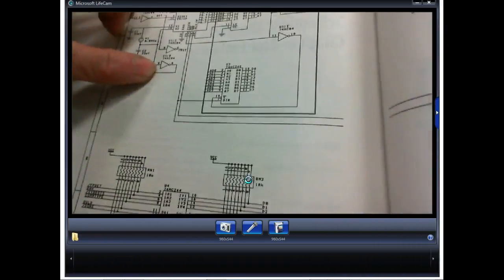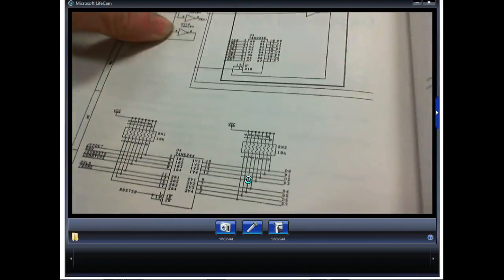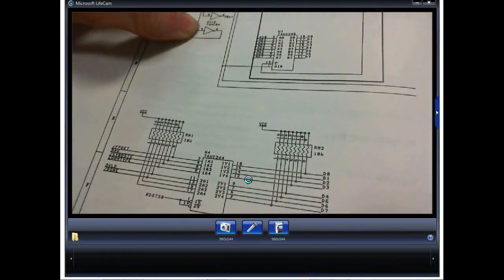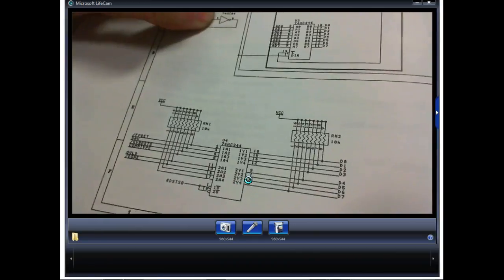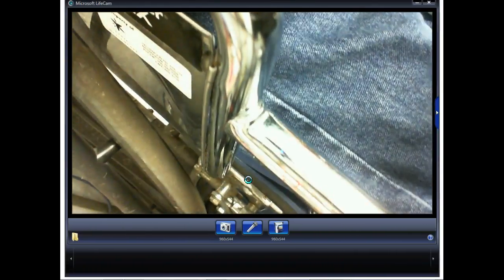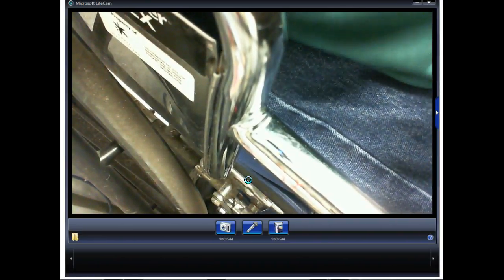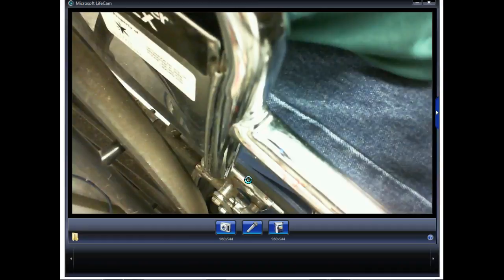So when you wire up a circuit, what do you think the first thing you're going to do? Well, the first thing you're going to do is take the schematic and you're going to assign pin numbers. Because you're going to be going between a data sheet and a circuit. If you and your partner assign pin numbers, then when you wire it up, one person's saying, where do I need to hook this up? Hook it up to pin 4, right? And you're looking on a schematic.